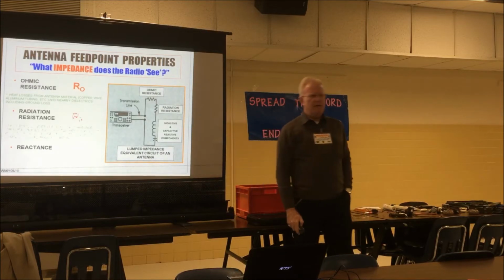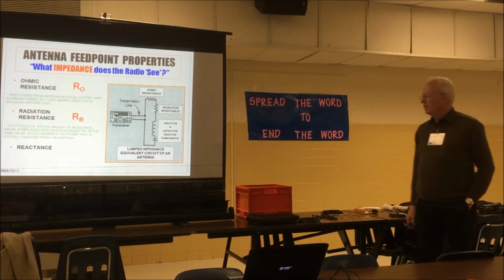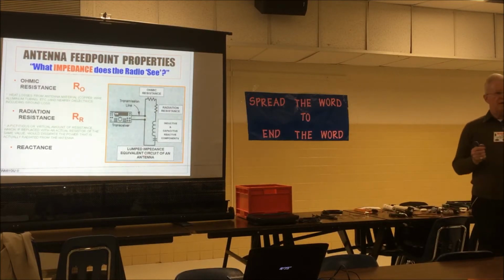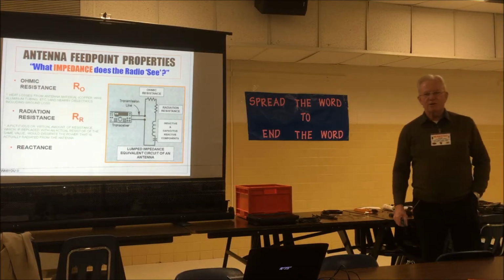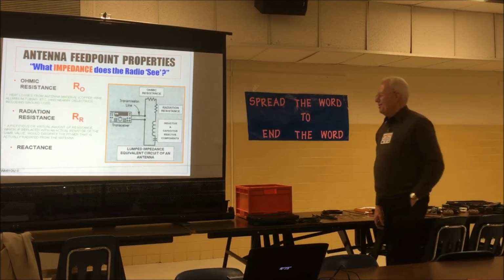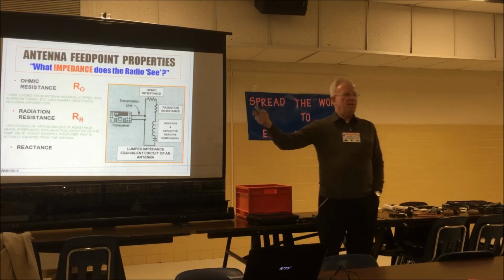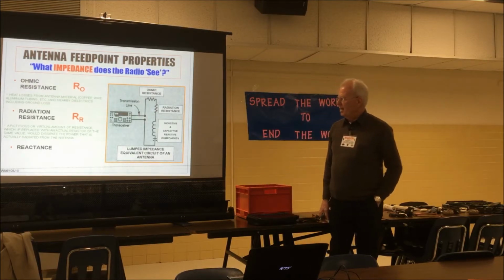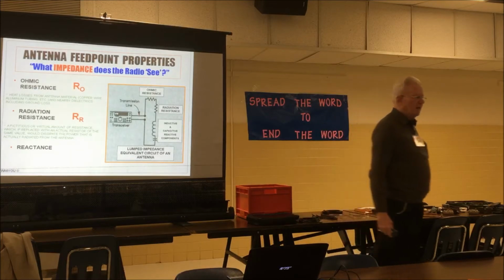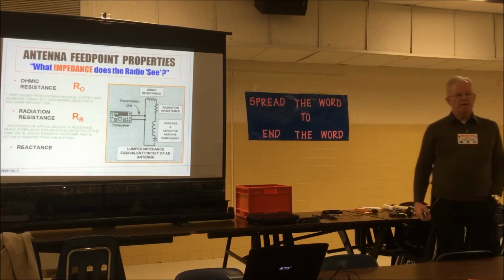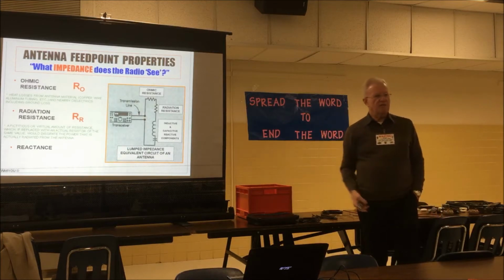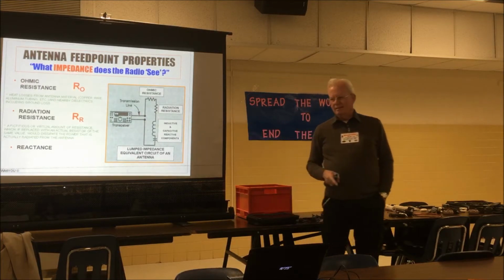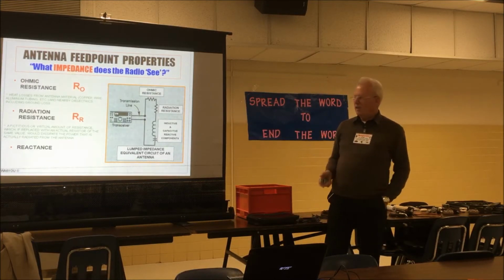The next one is called radiation resistance, and it's a fictitious virtual resistance. I still have students getting the ohm meter out thinking they can measure across the antenna and get 50 ohms. Radiation resistance, which if it's replaced by an actual resistor, would be 50 ohms on a perfect antenna. Very hard to explain. I go over some theories, 50 plus j0, and I have some XY charts that I use in class, but I won't bore you with that here. Just keep in mind that what we're looking for at home on our antennas is 50 ohms.